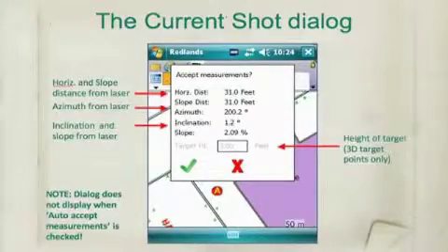That was what we did in Traverse. It took GPS to lock my first reference point in, and then let me work off of that single reference point without moving it. Or the kind of more traditional GPS offset mode people have been using for years, which is every offset I take needs a GPS point to associate them that way.